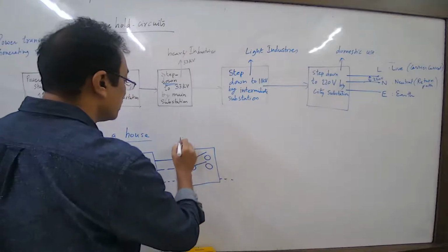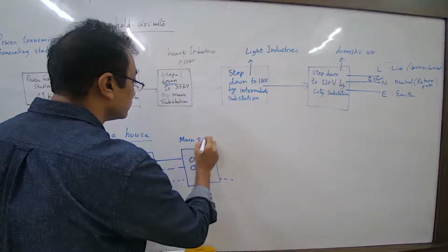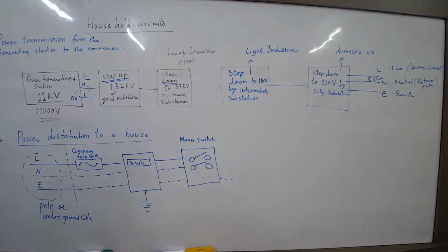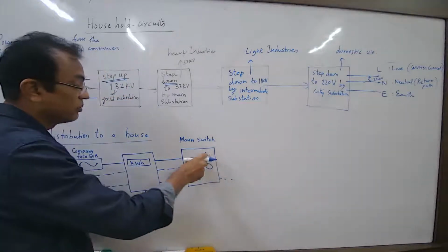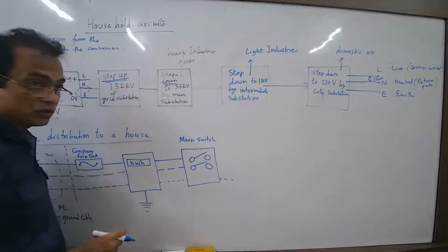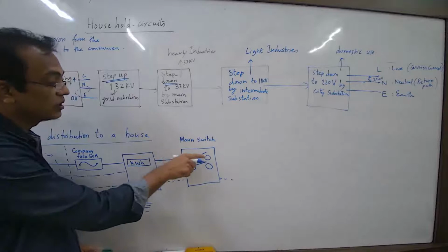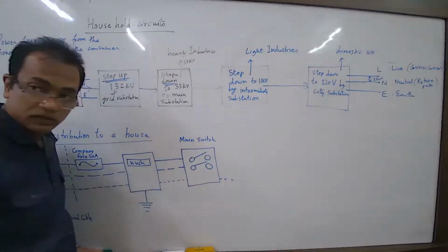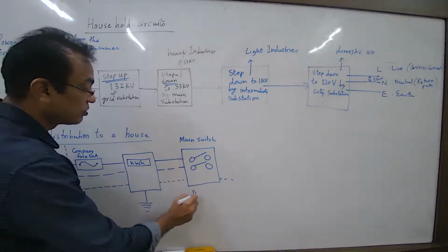So this is main switch. Is it main switch? Yes. Okay. So it's a double pole switch, right? Again, this is just the safety mechanism. So right now, is it open or closed? Open. Both contacts are up. This wire has reached here. If it is closed, then only it will go ahead. Otherwise, no. So double pole means it's a double pole switch.